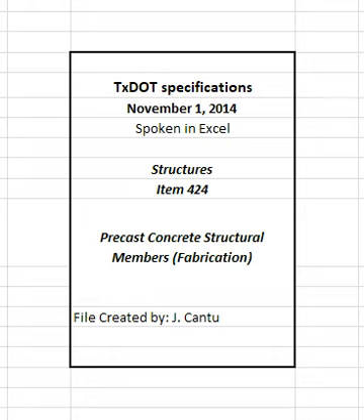4.2.4 Quality of concrete. Provide concrete in accordance with Item 421, Hydraulic Cement Concrete. Use the class of concrete shown on the plans or in the pertinent item for each type of structure or unit. Provide concrete meeting the approved mix design water-cement ratio. SCC is not allowed for project-specific fabrication plants unless approved by the engineer.